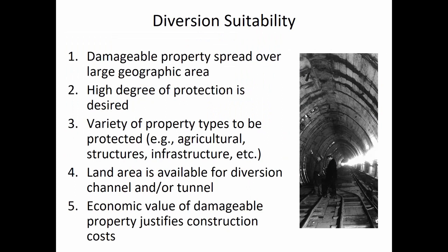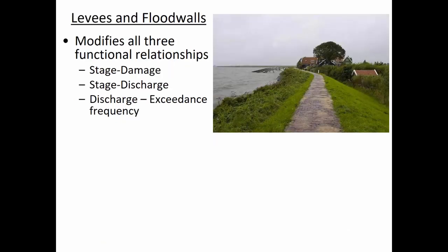Okay, diversions are similar to reservoirs, and so a lot of their suitability is similar to reservoirs as well. The suitability of a diversion is when what you're trying to protect is spread out over a wide area, and you want a high degree of protection, of a variety of types. All of the same restrictions apply for a diversion as apply for a reservoir. Levees and flood walls, though, are quite a bit different.